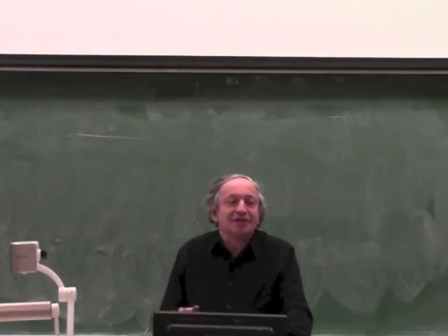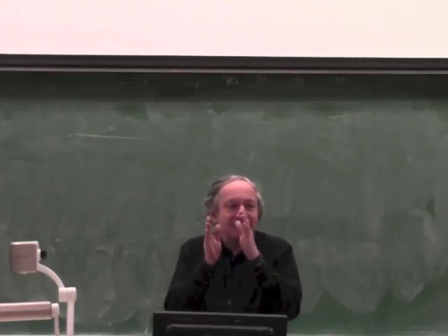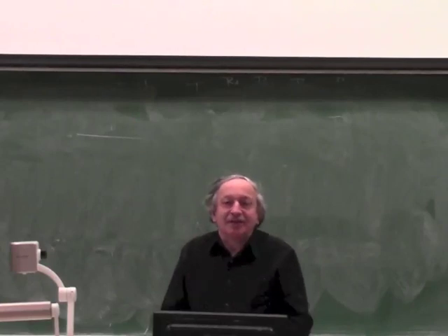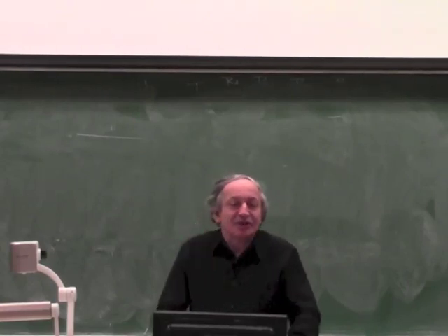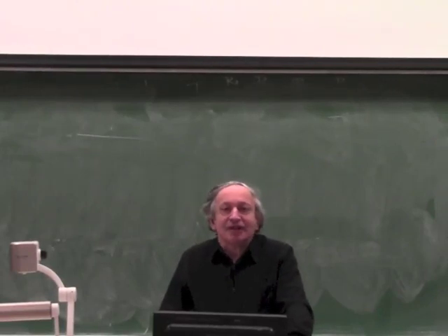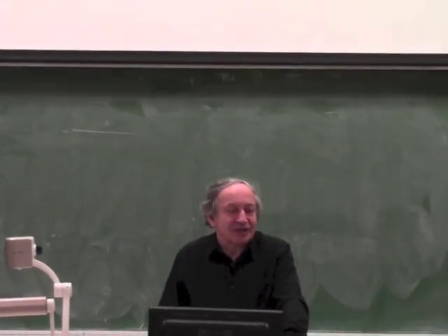That's the easiest. All you do when you make a MEMS is have a sacrificial layer, you etch it out, and you have a gap. And if you put a voltage across the gap, you get a force, and you can have a cantilever which bends and so on. So because of that, when you scale things down to very, very small, electrostatics are very useful, and because of MEMS, there are a lot of electrostatic actuators being used. So we'll devote one lecture to cover the theory of electrostatic actuators.